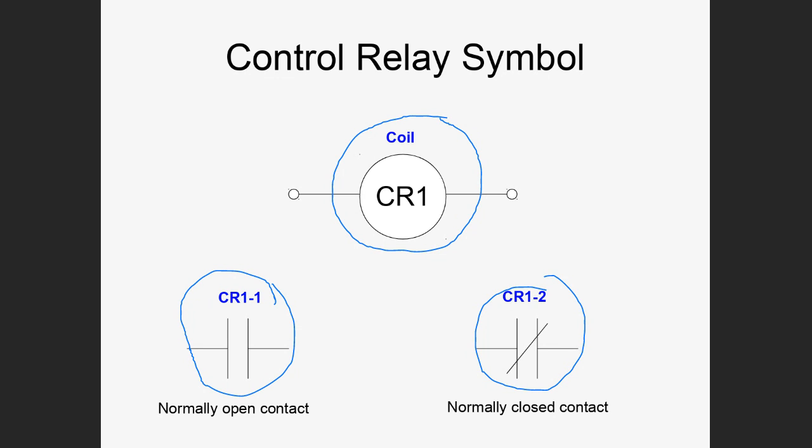You can't connect it directly to the output module, but since the coil circuit of a relay is a low current circuit, you can connect the coil circuit of a relay directly to a PLC, and then the actual armature can be as small or as large as you need it to be.